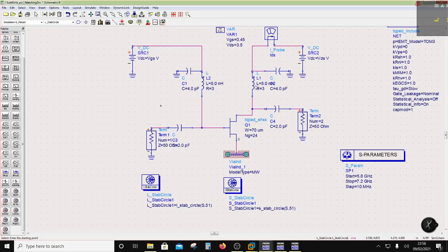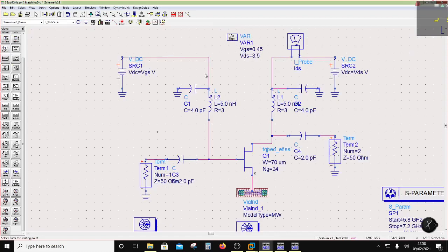So this inductor can be part of matching, but if you make the inductor part of matching, then you have to create a very good RF short here, which means that these capacitors have to be low ESR and they have to be large values, right? Otherwise you can put here a tank circuit or a quarter wave line for decoupling. If you want to use this as a part of tuning, then you have to have a very good RF short here, because otherwise the internal resistance of these batteries which you use in the physical world is going to affect your matching. So you have to create a very good short at these 2 points.